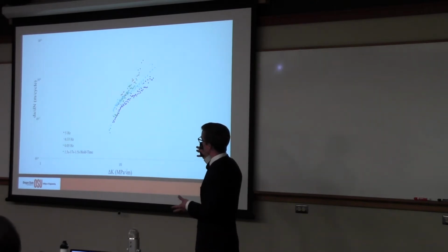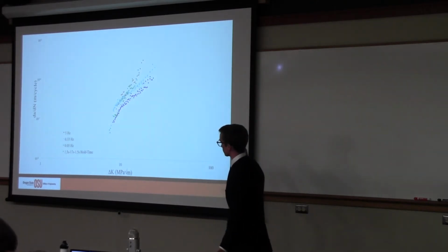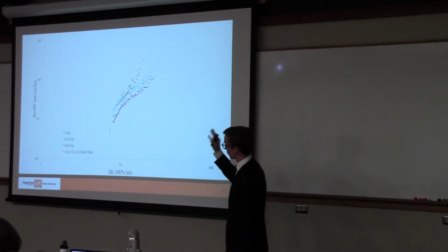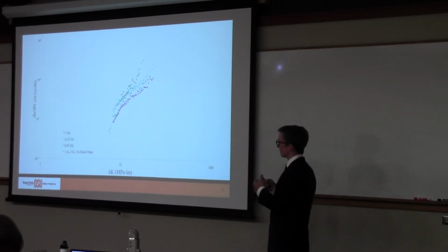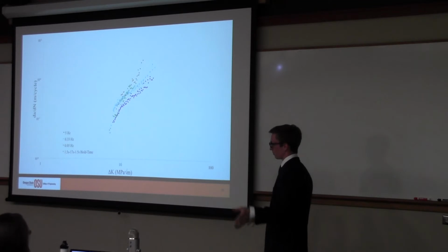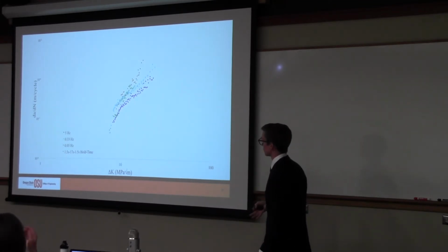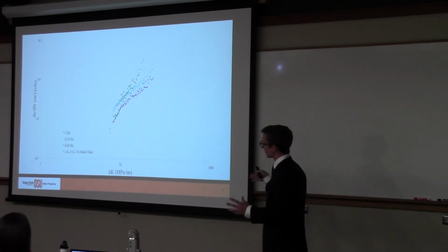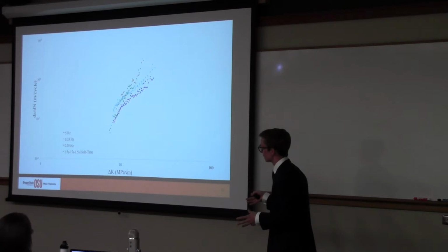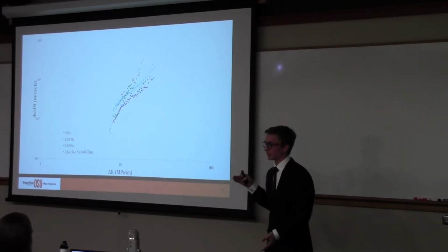And so there's a lot of dots that come out of the results. And this is a traditional domain for viewing this data: crack growth rate per cycle versus the stress intensity range. And I'm not going to cycle back through because I've got to make this presentation move as fast as we can. But the stress intensity range is derived from Pmax and Pmin.